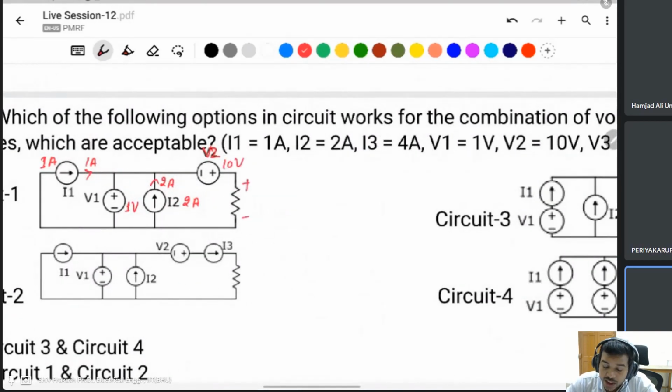This is a resistive circuit. In a resistive circuit you can take any voltage, because the resistance is not given here, so you can take the resistance as your desired value. First of all, talking about KCL. This is the 1 ampere and this is the 2 ampere. The remaining branch may take current or may supply current; it is not confirmed by the given data.